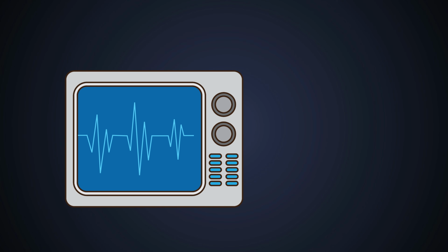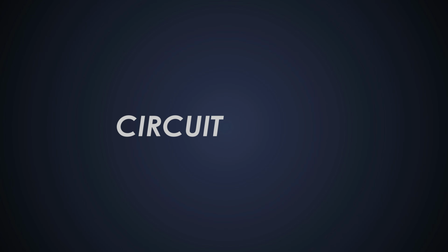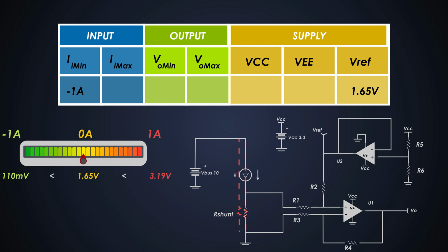energy. Now, let's take an example and see how we can design such a circuit, where the current in the circuit is in the range from -1 ampere to 1 ampere DC, and we need to provide this as a voltage signal from 0 to 3.3 volts. So we'll keep some margin and design a circuit such that 0 ampere current will be denoted by 110 millivolts and 1 ampere current will give us 3.19 volts out of the current sensing circuit. And for this circuit, we provide a VCC supply of 3.3 volts, which is sufficient, and we need to connect the VEE pin to ground.